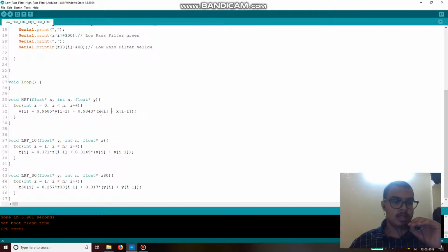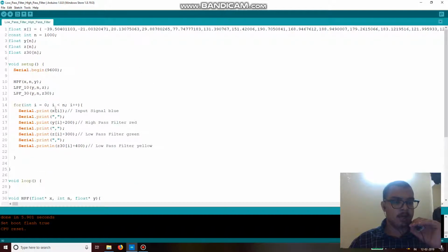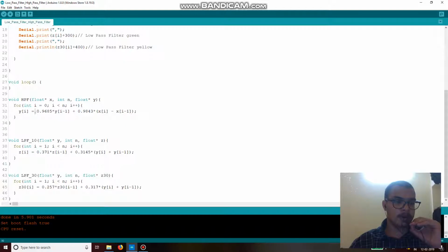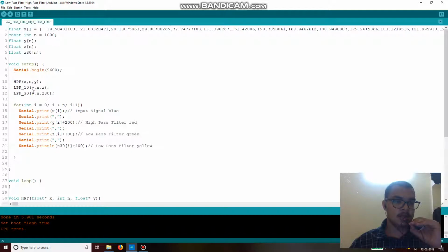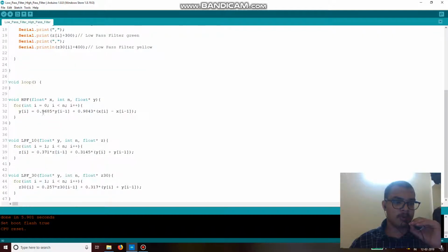And utilizing this formula, we are now able to pass the signal and have its high pass version. So y of i is the high pass version of the signal, which is basically y of i equal to 0.9685 y of i minus 1 plus 0.9843 times x of i minus x of i minus 1. This basically is a feedback based equation, as a previous term y of i minus 1 is also present. This is a for loop, and this does the HPF operation.